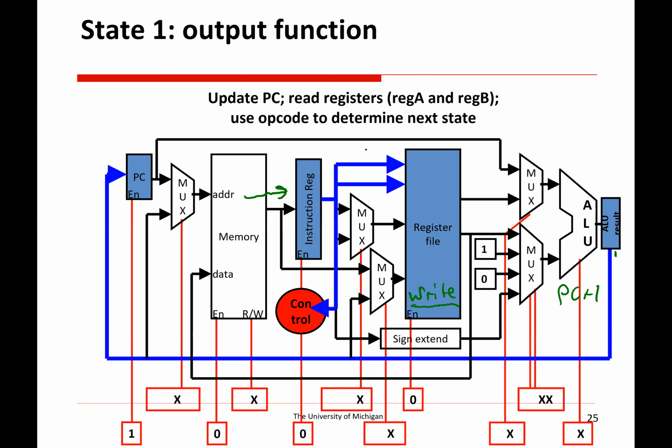But yeah, so once you have that, the reason we need a mux is because we're not always multiplying it by 2. Sometimes we're dividing it by 2, but that's just kind of the inverse. So just figure out how you would get that. Make sure that it's working correctly with the edge cases of negative numbers.